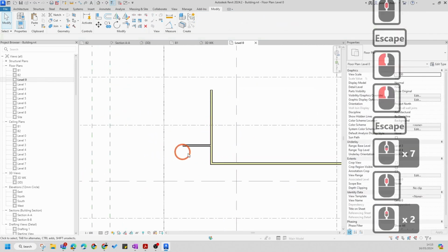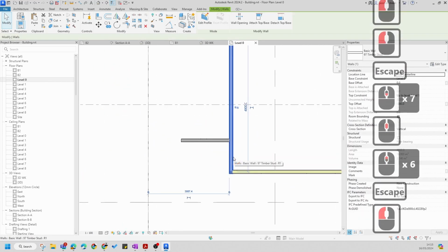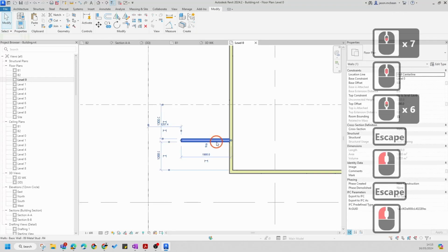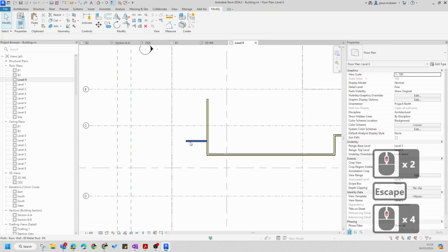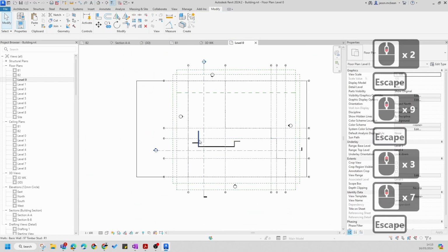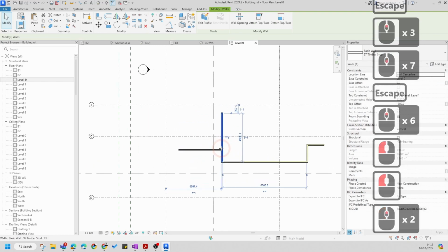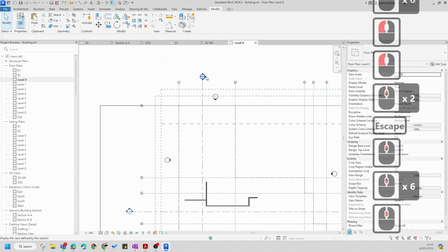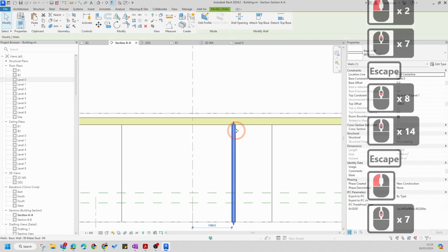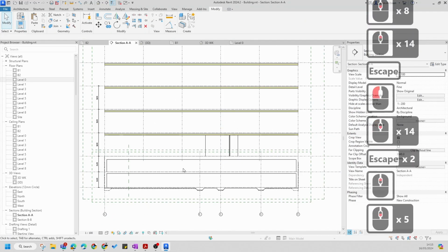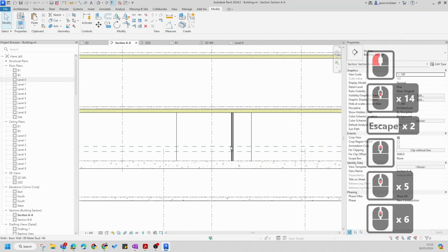But in essence, we've got a timber stud wall and we've got a metal stud wall. They're always going to finish with an offset underside the slab, so that's important to know. I'm just going to drag this wall back, and you see they keep that relationship. So you can see that works pretty well. So we've learned to make some floor types and wall types.